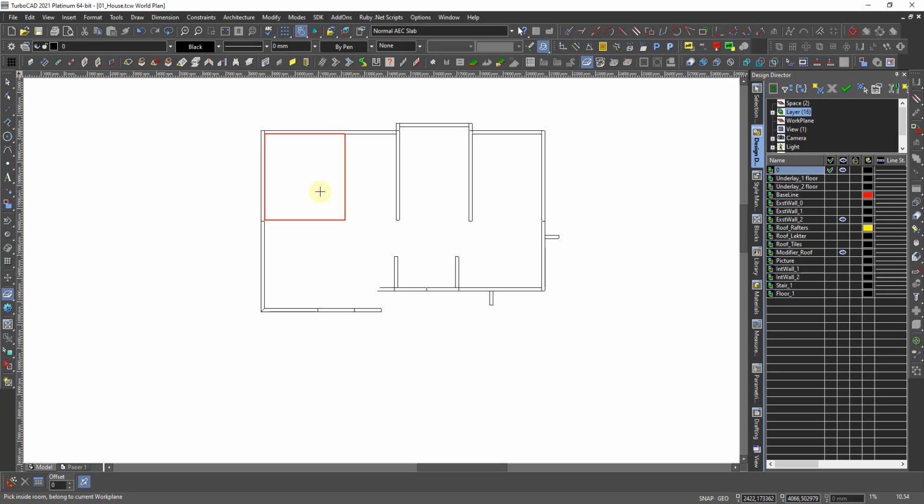that. And also later we can take and show why the interior wall should stand on the same level as the exterior wall because of the linkage or have connection. And because if the interior wall stand like we build it, normally we build it, we put it on the top of the floor, not on the bottom. But then we cannot get this later when we want maybe to put some parquet or something like that on the floors. So that's why we have to do it this way.